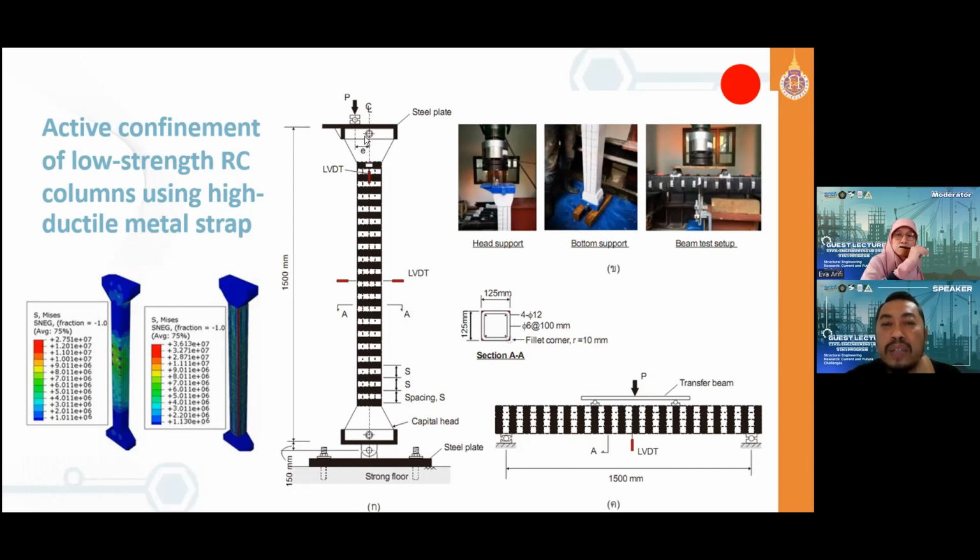So we are trying to obtain the moment and axial interaction diagram. We have the axial load there, and we have the eccentricity there. So when we apply it, we have both moment and axial combined. And when you move P here to the center point, you have purely axial load. And then we also do the pure tension like this. So combining these, you can develop your own PM diagram of these confined columns. Okay.